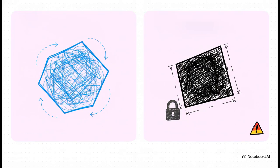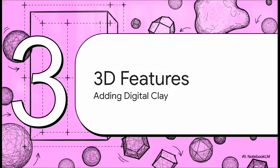Now, this brings us to a universal pain point that you absolutely have to master. When you draw, your lines start out blue. Blue means underdefined, meaning they can be accidentally dragged and completely ruined. You've got to use smart dimensions and geometric relations, like making 2 lines perfectly parallel, to turn those chaotic blue lines black. Black means fully defined and securely locked into place. Just be super careful not to over-dimension, or you're going to trigger those dreaded red and yellow errors that will absolutely haunt your nightmares. Okay, section 3, building 3D features.